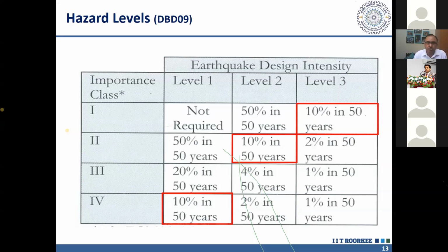So ZY2 is actually serviceability earthquake, and 0.75 Z or 1.5 Z divided by 2 becomes DBE, and 1.5 Z becomes MCE. That's why our code uses a load factor of 1.5 on earthquake. If you see other codes of the world, which are based upon probabilistic seismic hazard, there the definition of MCE or DBE is given directly. And in that case, the load factor for earthquake is 1.